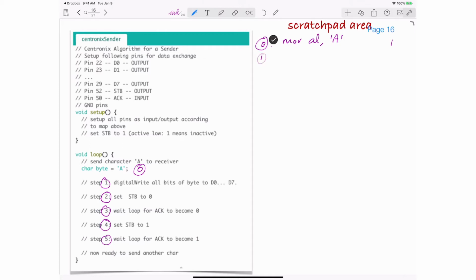So step 1, how can I do that? Well, in a Pentium, we don't cover that typically in the assembly class at Smith, but there's an in and out instruction for outputting a byte to some port or inputting a byte from a port into a register. And usually AL is a register that is being used. So here I could imagine that I could out to some, say, D0 AL, and that would be enough to send the least significant bit of AL into some port and be out. So I'm going to assume it's going to take 1 instruction.